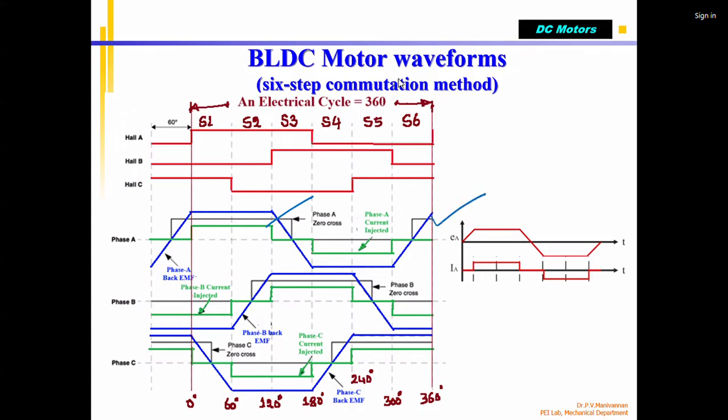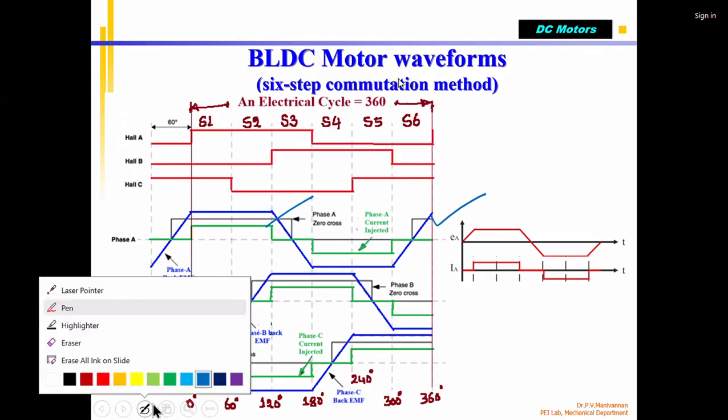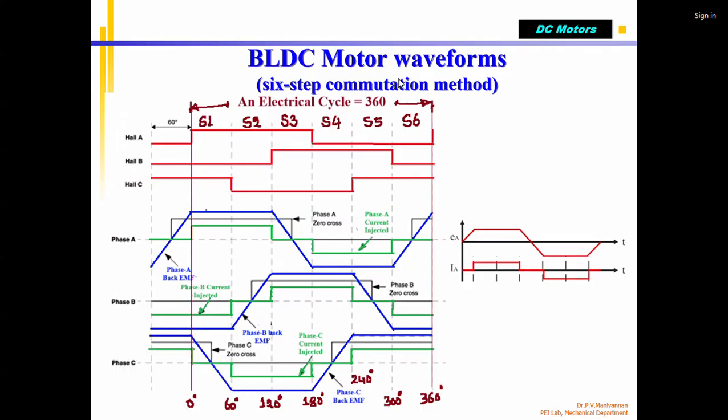The same thing happens for the other phases, but each one is separated by some distance. This is the first phase, and this is called 6-step commutation. On the board, this is step 1, S1. Each step is 60 degrees, as you can see from the dotted lines. This is the second step, 60, 60, and the last 60. So in total, this is 360 degrees.